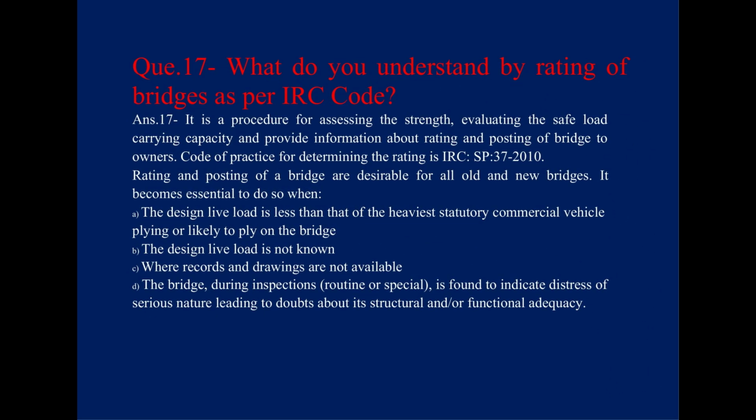Question: what do you understand by rating of bridges as per IRC code? Answer: it is a procedure for assessing the strength, evaluating the safe load carrying capacity and providing information about rating and posting of the bridge to owners. Code of practice for determining the rating is IRC SP 37-2010. Rating and posting of a bridge are desirable for all old and new bridges.